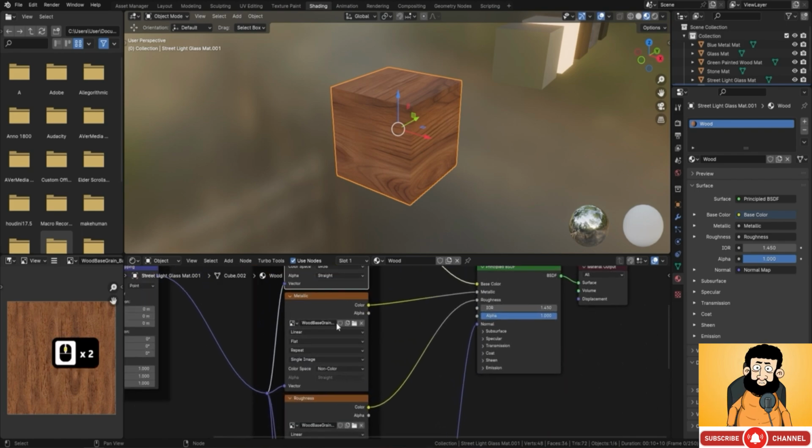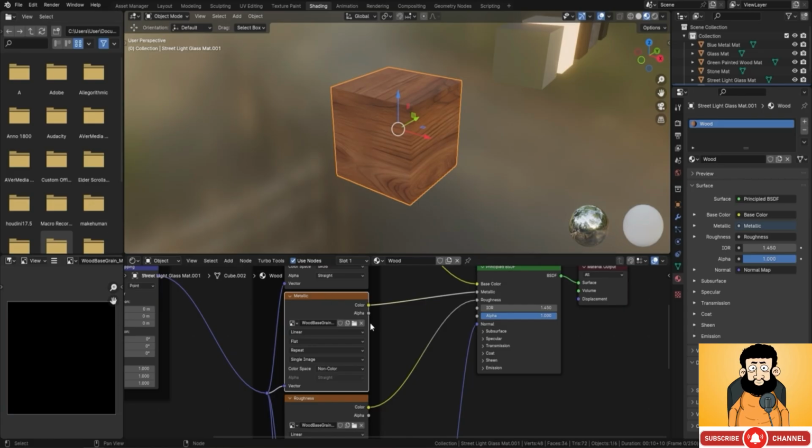If we go to the next one, we've got metallic, and this map defines which parts of the texture are metallic and which are not, influencing how the material reflects light. Metals have a high reflectivity and distinct coloration in their reflections. Now you will notice if I click on this one, it's completely black because this wood has absolutely no metallic. If this was completely white, all of this wood would be completely metallic. And if it has kind of grays in there, that then defines the roughness of the actual metallic. In other words, those little spots that you see when you shine light on something.